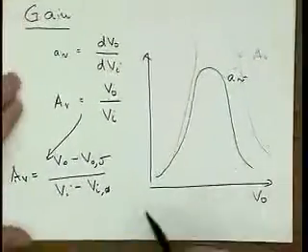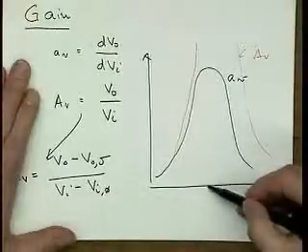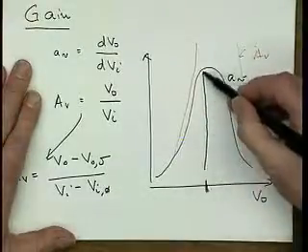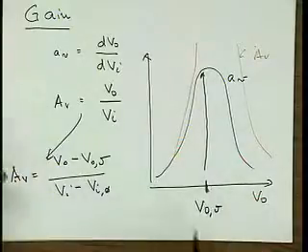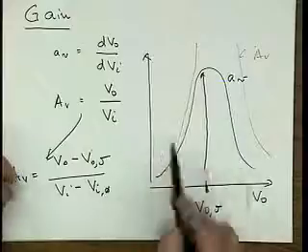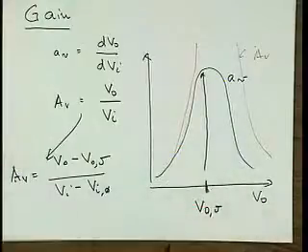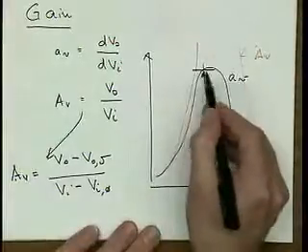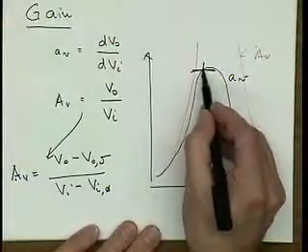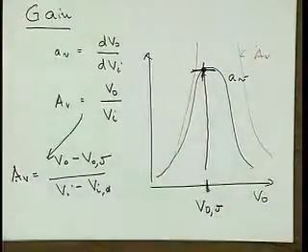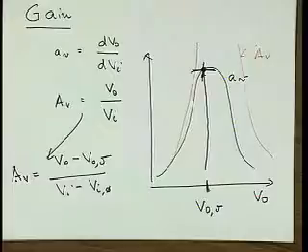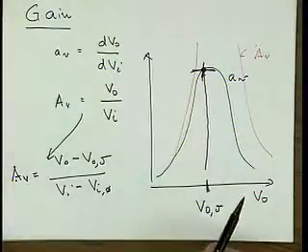In other words, there is one point which we call Vout0, and there is also a corresponding Vi that I need in order to get this Vout, not on this graph. And that's my bias point. And if I evaluate the gain at that point, the large signal and small signal gain are going to coincide at that one particular point. And then as I deviate from there, they're going to differ again.